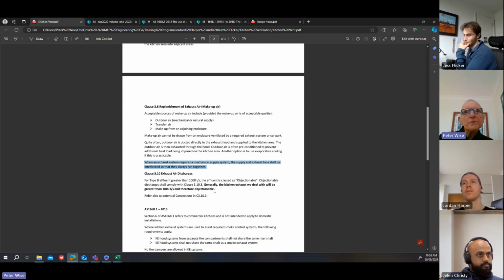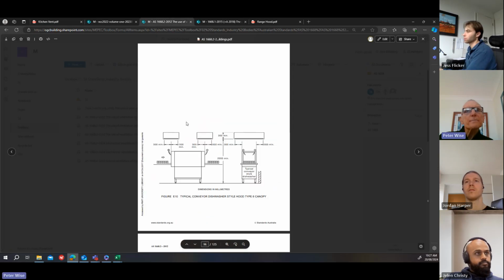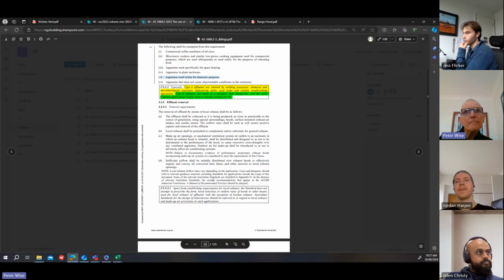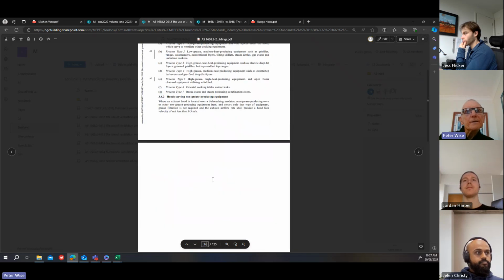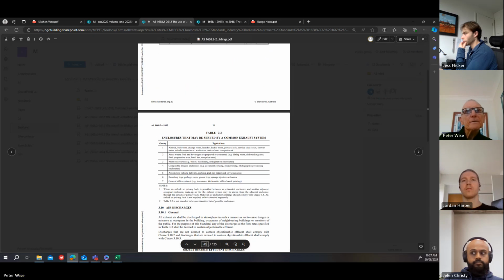Now, exhaust air discharges. Clause 310, for type B effluent greater than 1,000 litres per second, the effluent is classed as objectionable. There's non-objectionable and objectionable discharges defined in AS 1668 Part 2. We'll just go back to there. I don't know whether you're familiar with those terms at this stage. Go down to 310. So they're quite important to be aware of.